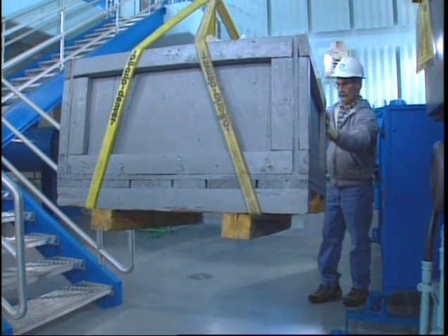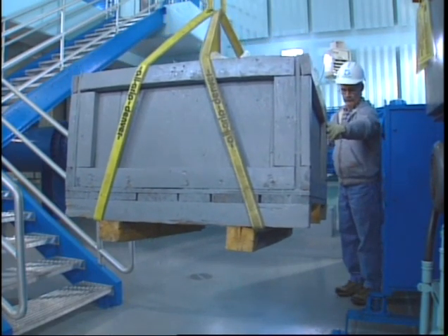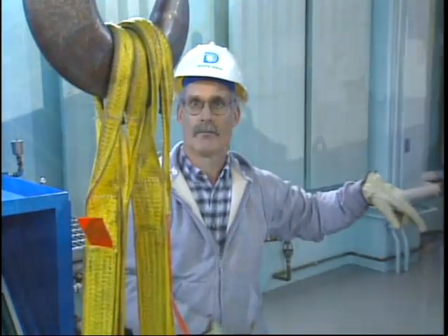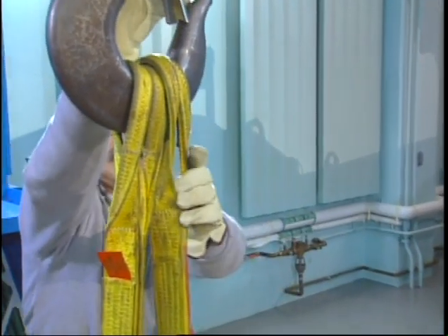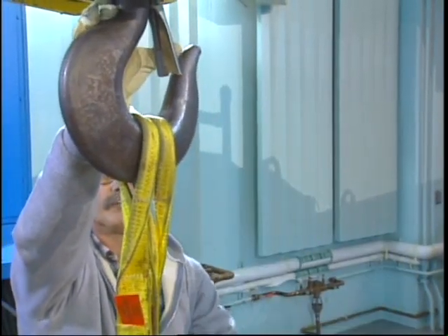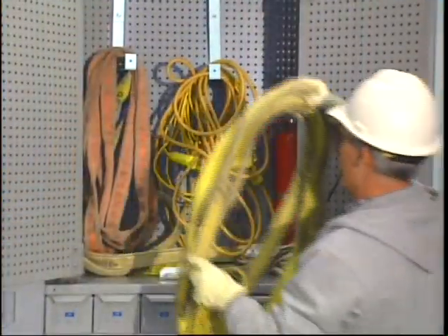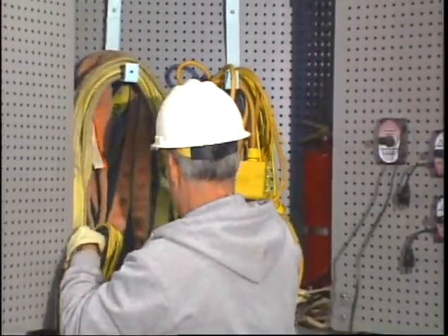After transport, when possible, the load should be lowered to rest on blocking material so it doesn't damage the sling. Once the load has been moved and all tension has been taken off of the hoist, disconnect the hook, carefully remove the rigging, and store it in a place that is safe and dry.